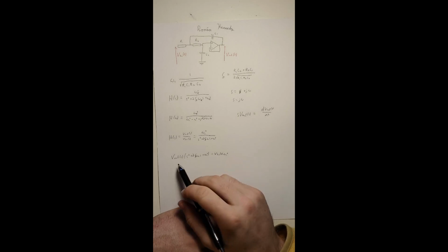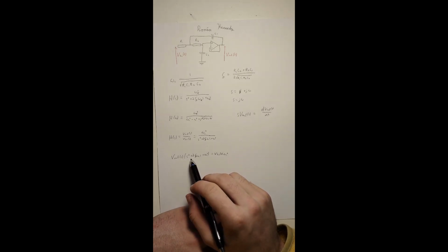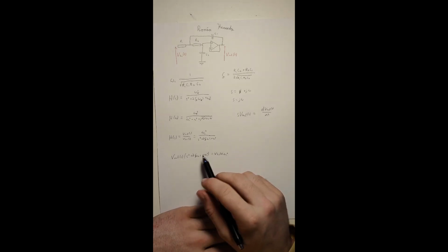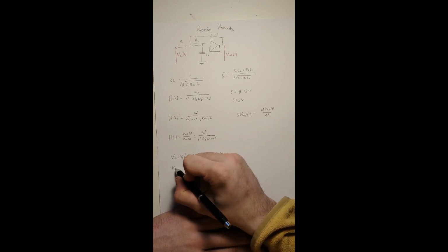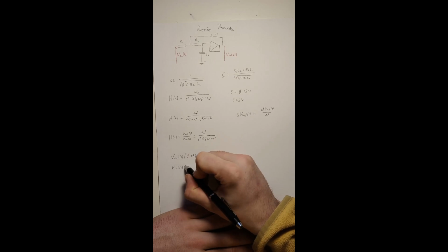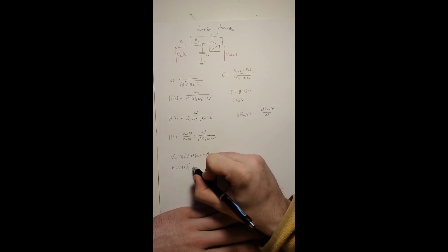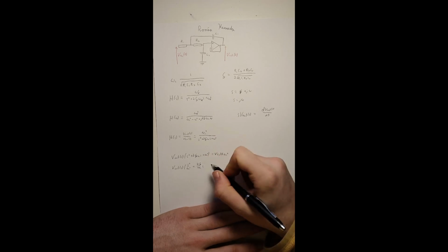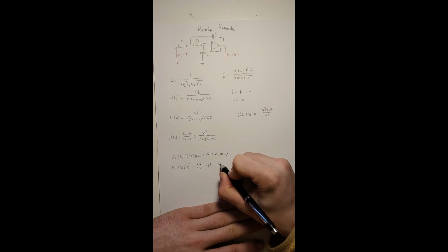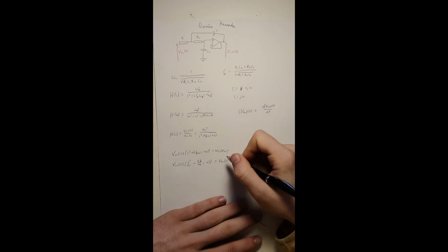So the only time where V out is multiplied by an s is here. So we want to make that equal to 1. So if we divide both sides by omega C squared, then we'll have it equal to 1. So we'll do V out of s by s squared over omega C squared plus 2 zeta over omega C s plus 1 equals V in of s.